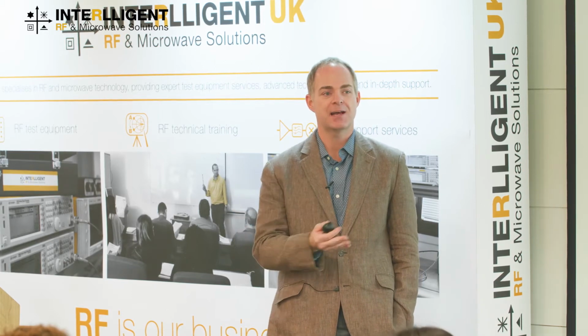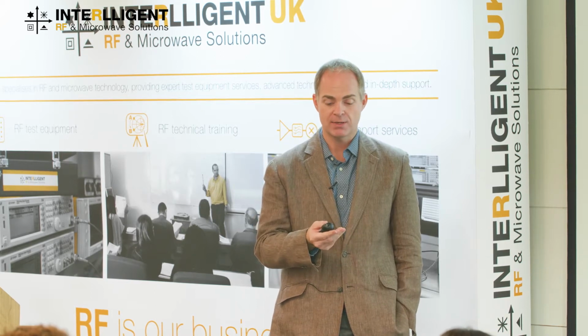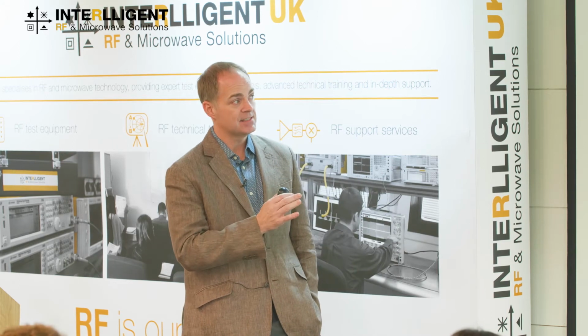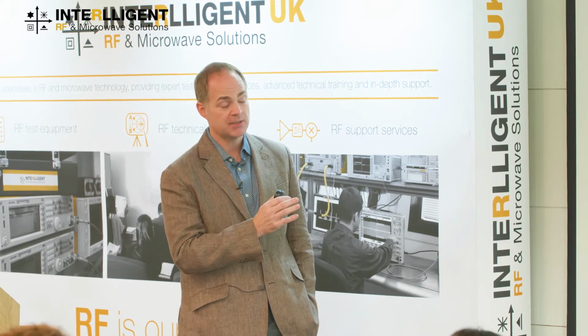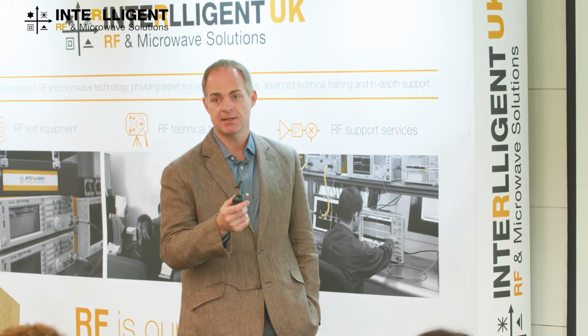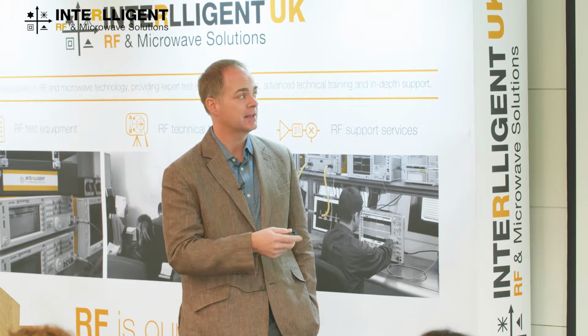A lot of these applications, particularly as you get more into the base station and larger power needs of some of these applications, GaN as a wide band gap semiconductor can provide much higher power densities due to the higher breakdown and the higher current capabilities. The next most important thing is thermal handling.